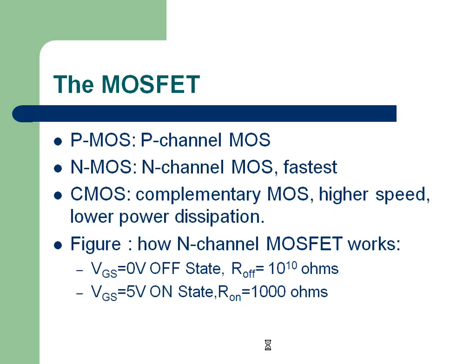For example, a simple CMOS won't be able to create high impedance. What is required to create high impedance we will study subsequently. In a simple CMOS case, if the PMOS is off, it offers 10 gigaohm impedance. It is like an open switch. When this is off, the other will be on, so that will have only 1 kilohm.